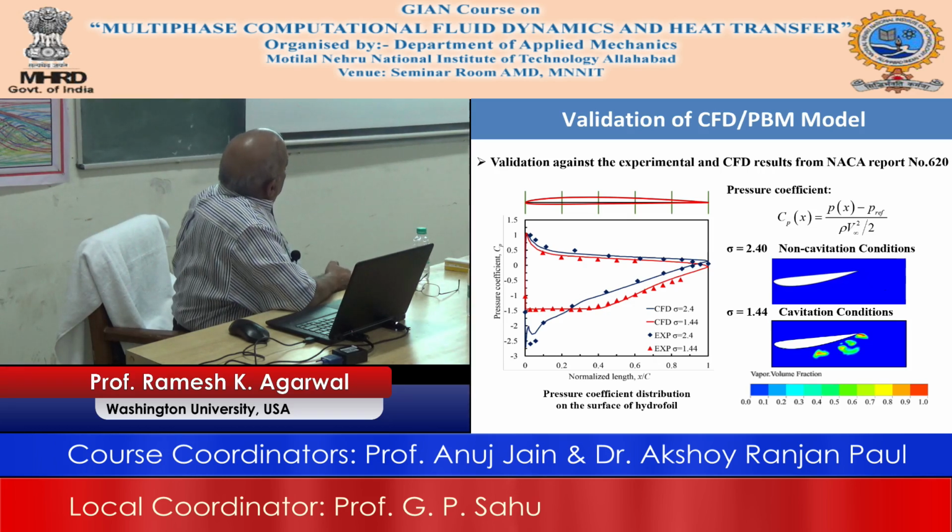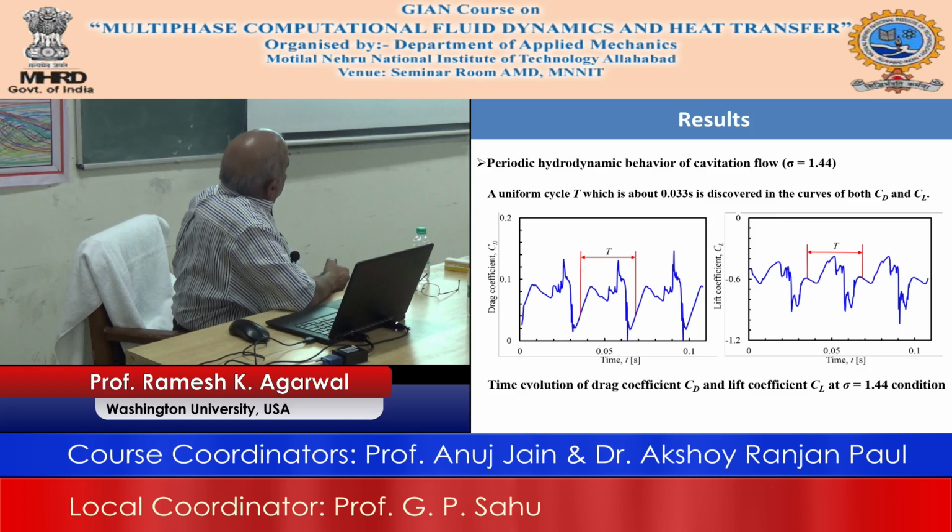It turns out that there is a periodicity in that solution in the case of cavitation, and so the lift and drag over the aerofoil is changing in this fashion. You can get all this information, and then it goes into some more detail on how this cavitation is changing as you go from T0 to 1.0.